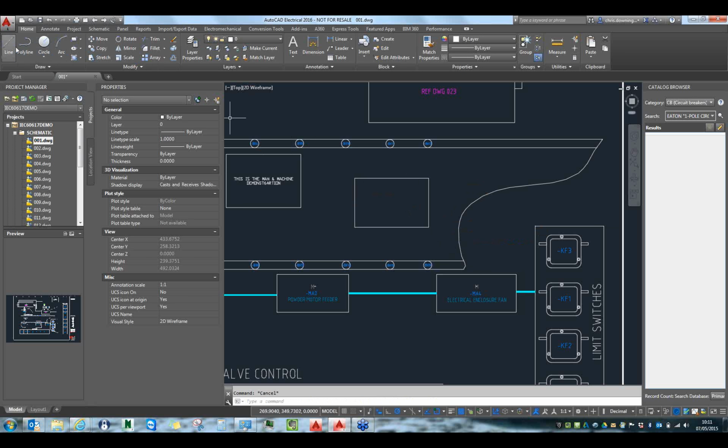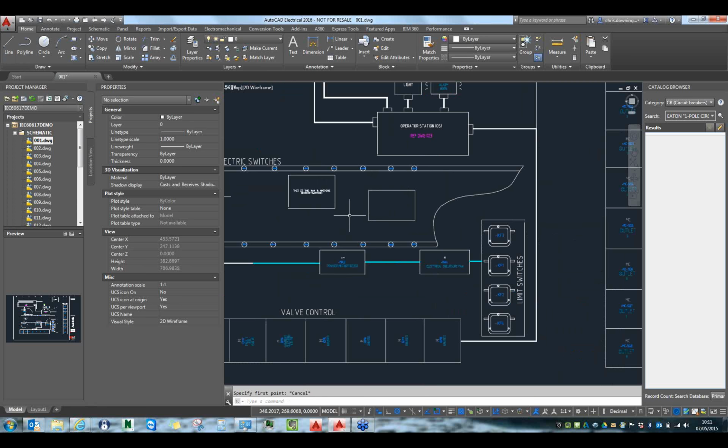You remember previously you'd have to snap to the midpoint of two sides and find your midpoint of this rectangle, but now we can snap to the center of a rectangle automatically with the geometric snap option on. There we go. So that's quite a neat little tool.